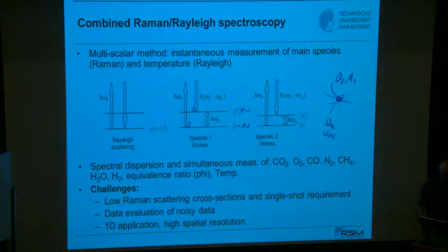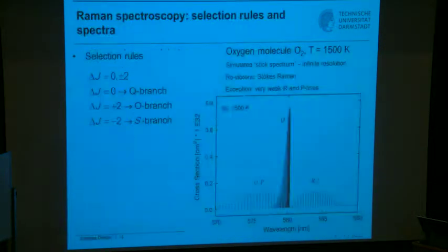Nowadays, of course, we want to do that 1D. Why that? Of course, with high spatial resolution. We are interested very often in this context really in the structures of flames. And that means you want to have derivatives: in non-premixed flames, scalar dissipation rate; in premixed flames, thermal dissipation rates. And for those gradients, you need at least along a line the information about these scalars.